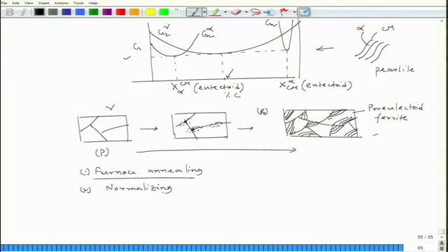That time the structure modification would be there, the structure would become like this, the grains would be much finer, which is alpha grain. I am talking about the final microstructure we will get. And also pearlite would form. So, this pearlite would form.